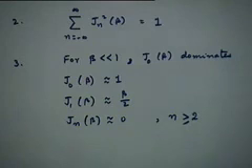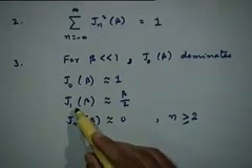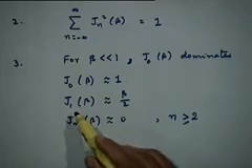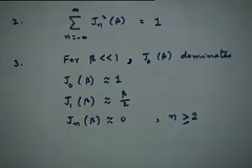That when your modulation index is small, out of all this infinite number of terms that this expansion has, only 3 terms will be the most significant, one corresponding to n equal to 0, one corresponding to n equal to 1, and n equal to minus 1. That means the spectral components that you will see will be primarily the carrier frequency, which is for n equal to 0, and omega c plus omega m and omega c minus omega m.